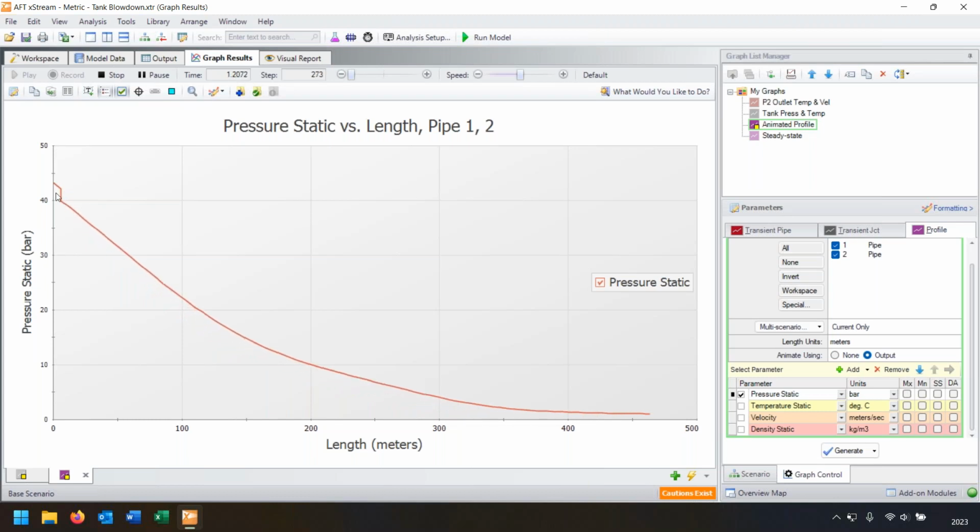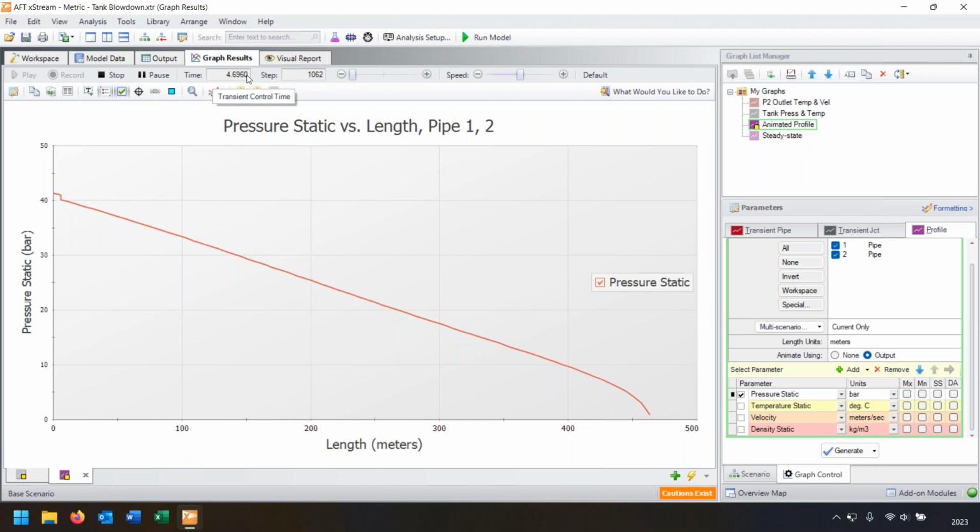So here we're at 1 second, so our valve is no longer the limiting factor, and our pressure wave is close to reaching the end of our system, where again, we're getting more and more pressure built into the system. And here you can see it's starting to sonically choke. You see that higher velocity, that higher pressure loss as it goes through the end of the piping. And it continues until we should see something approximating our steady state value. So if our question was, hey, when do we achieve a steady state pressure profile or something close to steady state, it would be about 4 seconds.